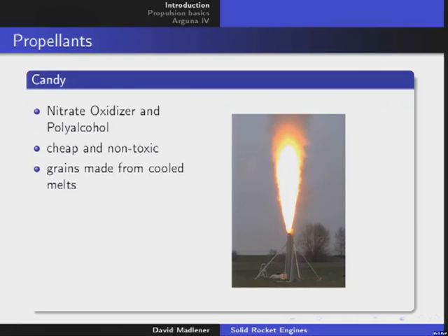But of course, you have to be very thorough with your temperature curve. So you have to do it, in our case, at between 130 and 140 degrees Celsius. And you have to do it very smoothly, you have to turn it around, and after a time, you just cool it slowly down. So it needs some hours to cool down and some days to be usable.